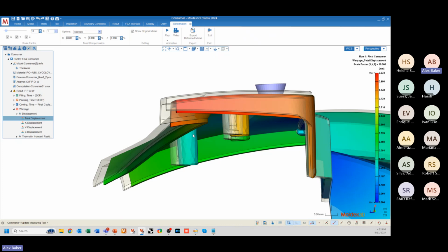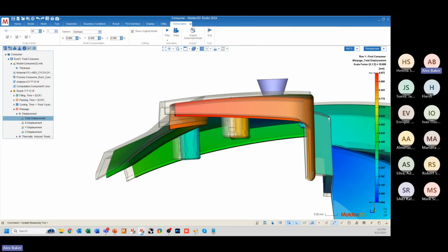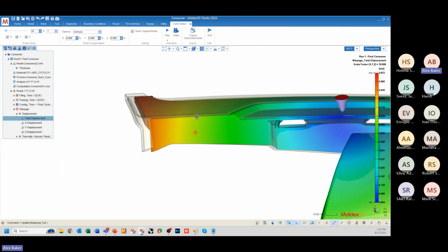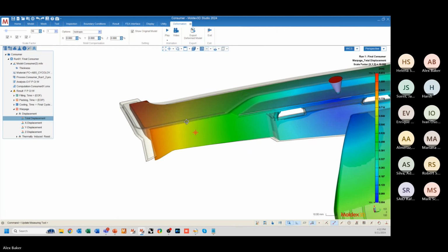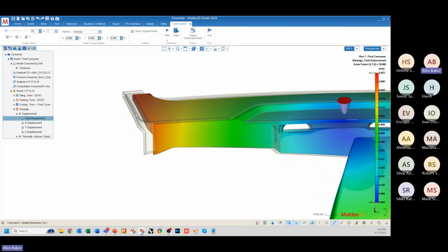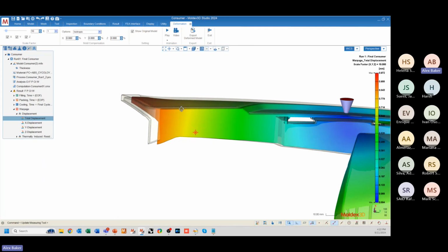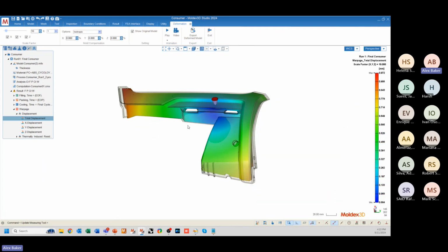And we don't really see a whole lot of movement, maybe a little bit towards the right side in the Z direction, but really not too much there. So I would say that this is mostly just linear shrinkage. There isn't really too much deformation happening here. It just looks like this is all shrinking towards the center of the part.